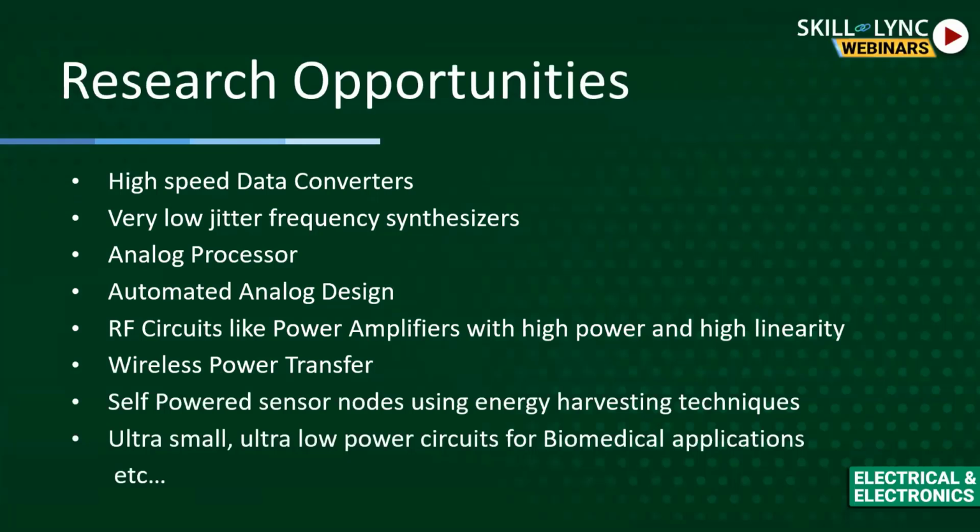These are the data converters, analog to digital converters or digital to analog converters. It's a very wide, actually very important research topic, because today what we want is that as soon as we get a signal, we give it to the ADC, and it's actually not possible. It is possible if we can build a very low LSB data converter, and generally noise is what precedes the signal that we get. That's why we have an amplifier before this ADC. So it's a research topic which is very widely taken by students.